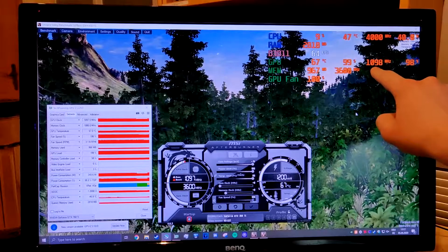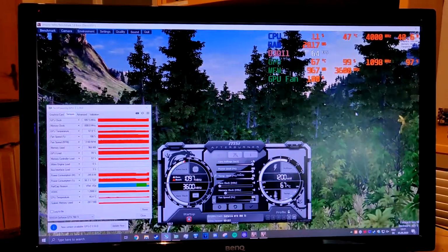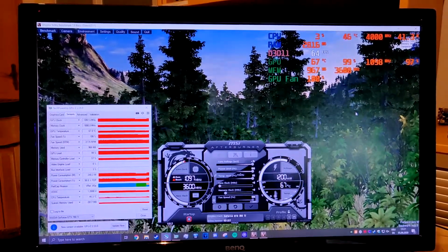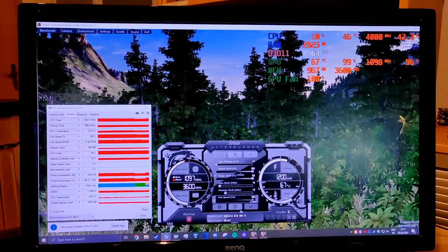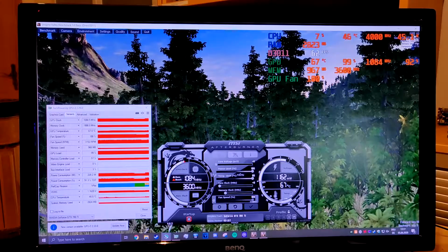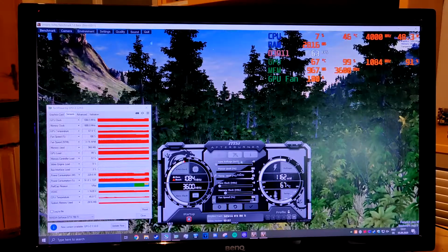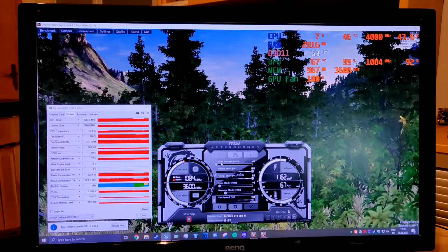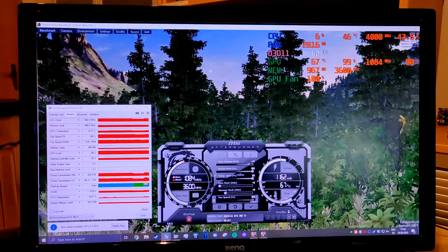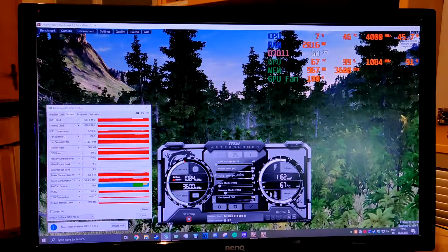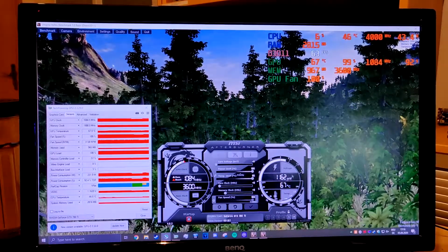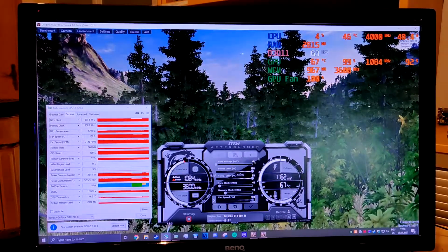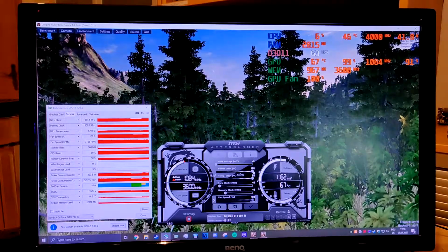We are at 1098, not 1084 as before. So the GPU boost algorithm here also factors in temperature and voltage and all that. Just on newer cards, this voltage slider won't actually change the voltage anymore. It just will tell the card you can stay at the highest voltage for longer, whereas here it will actually increase the voltage. But back to the power limit, which this is about.